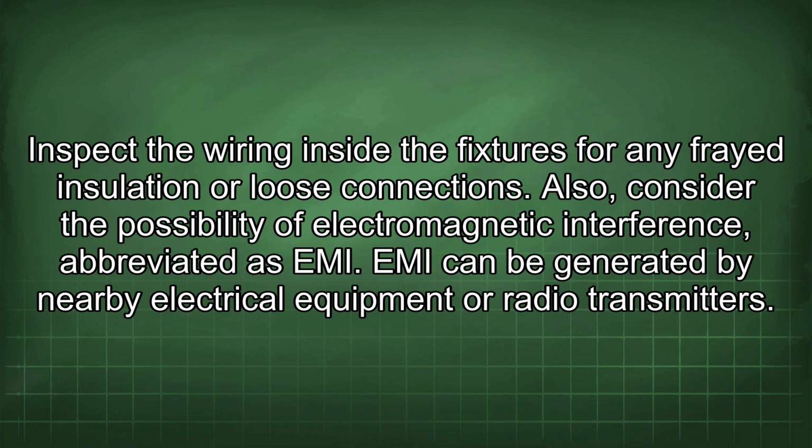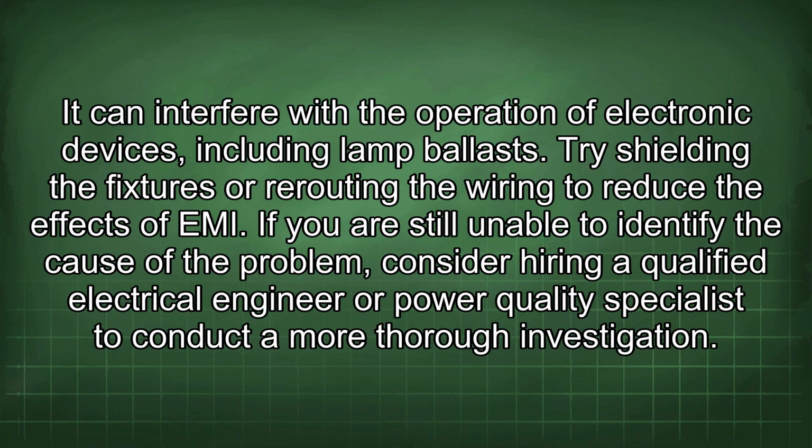Also, consider the possibility of electromagnetic interference, abbreviated as EMI. EMI can be generated by nearby electrical equipment or radio transmitters. It can interfere with the operation of electronic devices, including lamp ballasts. Try shielding the fixtures or rerouting the wiring to reduce the effects of EMI.